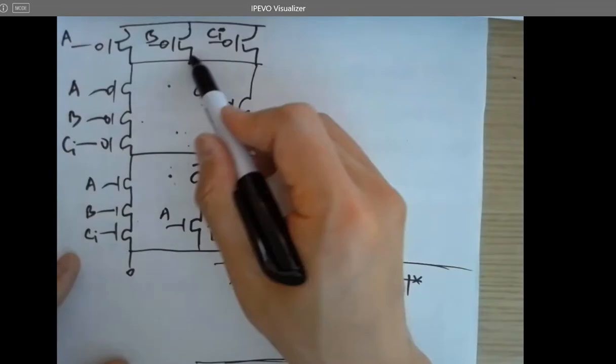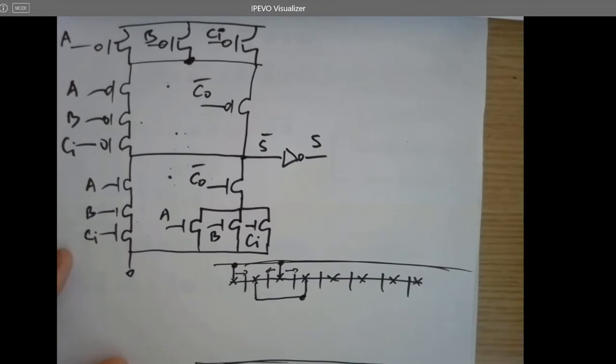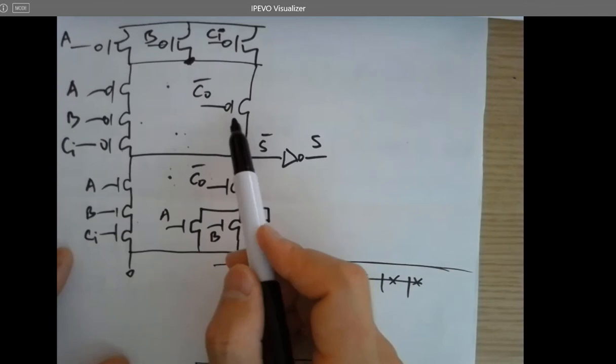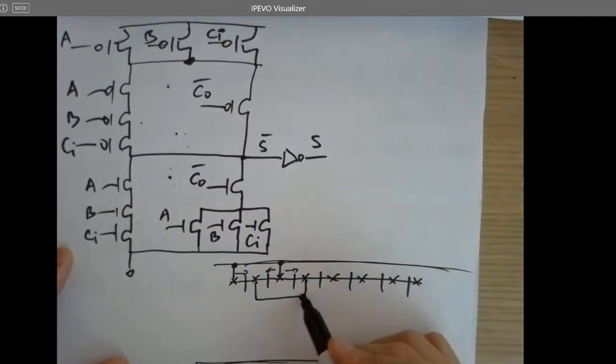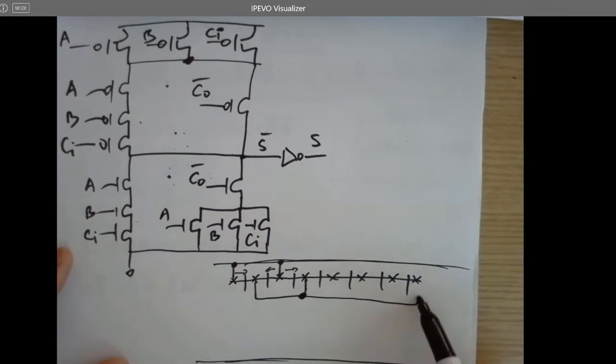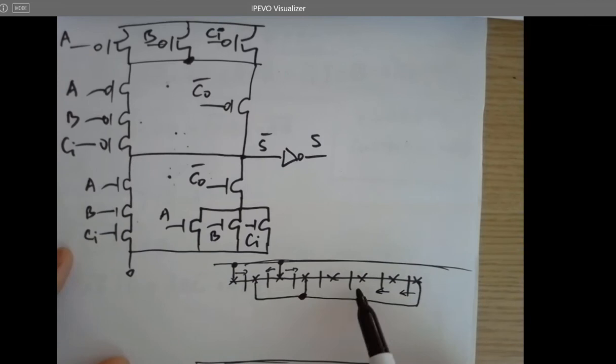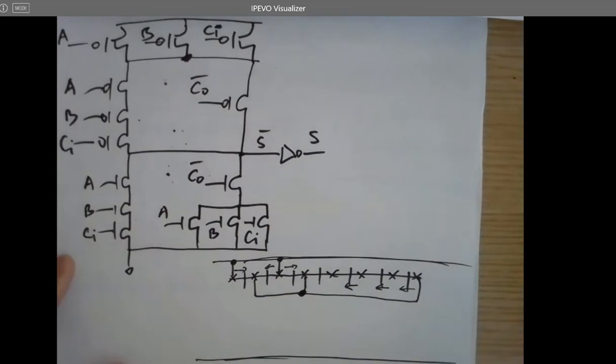So this node is here, and then 3 PMOSes in series. How to do that? So three more PMOSes in series and in parallel with 1 PMOS. So you got 4 PMOSes here. How do you want to plan on this? Because we know this node is this node. So if I connect this wire to here, it's going to directly flow through 1, 2, 3 PMOSes. Will that work? Would this work? How?